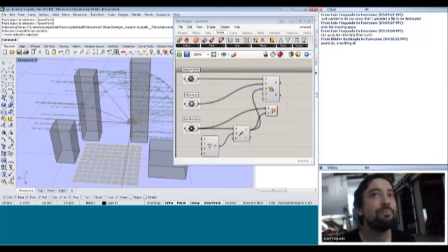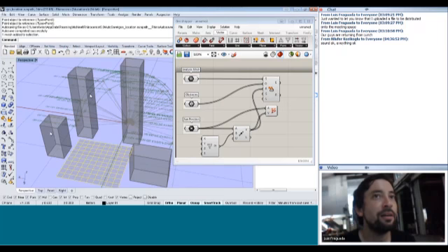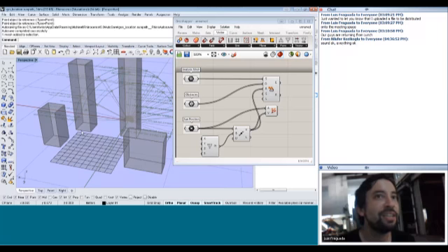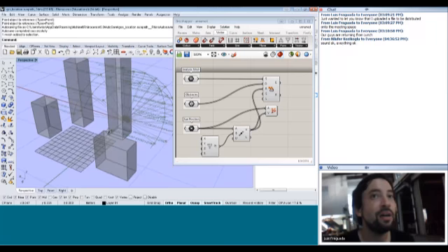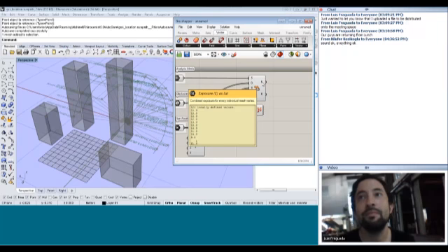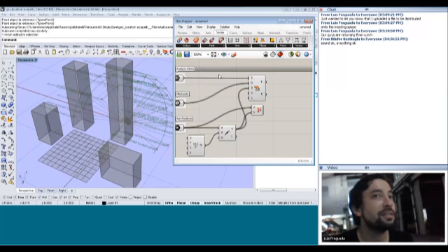At some points, it might be obstructed by these buildings, so it doesn't actually reach there. So for each of my points, I now have a different value. For each of the vertices of my mesh, I have a different value for exposure, which is coming from E. At some point here, there are 15 rays that actually hit it. At another point, there are 13 rays that hit it. At some other point, there are 21 rays that hit it. So because of my obstacles, this is not being exposed in a similar way. Each point has its own particular exposure that now we can see.